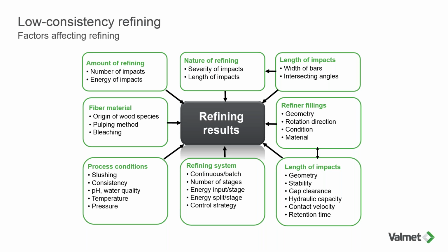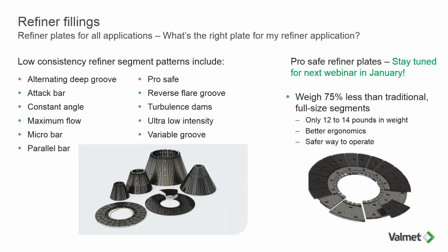So all of these are taken into consideration, but are we using the correct plates for the particular application? And that's something that we need to address each time and specific for each application. So each one of those parameters that you saw on that last page briefly are impacting the selection of the refiner plates to get the right properties for your finished good. So there's a whole bunch of potential selections of refiner plates, a lot of geometries depending on what kind of refiners you have out there.